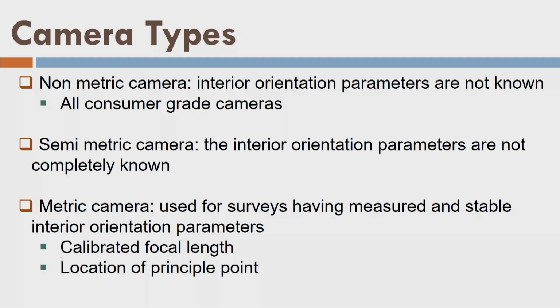In fact, when we go for photogrammetry, this length is not perfectly known. It could be 18 mm, it could be 19 mm, it could be 18.5 mm. For photogrammetry, for 3D measurement, focal length plays a very vital role, and we should know its exact value. And that is why we go for the calibration process, where we determine the exact calibrated focal length, right?